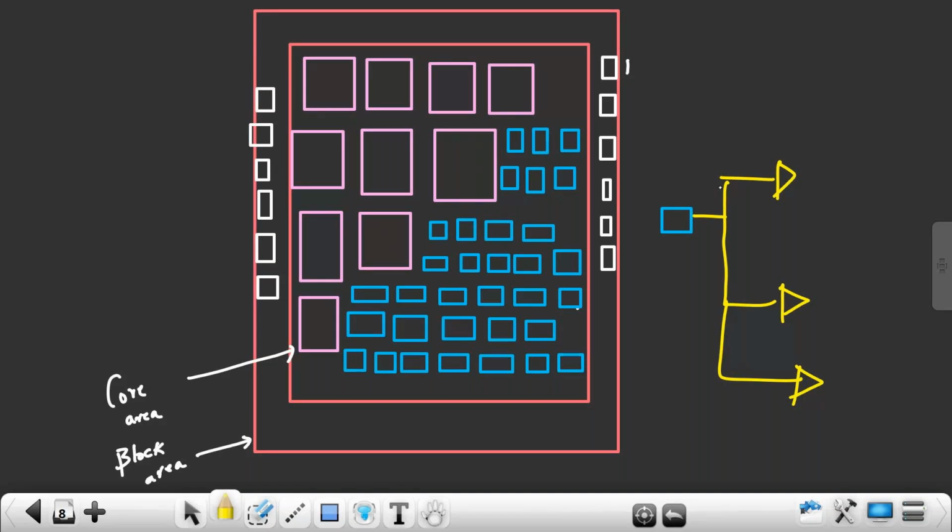Now this port is driving how many buffers? Only 4 buffers. So I will be having load here. How much is required? This pin capacitance plus this net capacitance. So how much capacitance is it going to form? Only that much load I will be having. I have less load here, right? So as I am having less load, my clock will easily rise, easily fall. So I have pulse width. My clock will rise and fall like this.